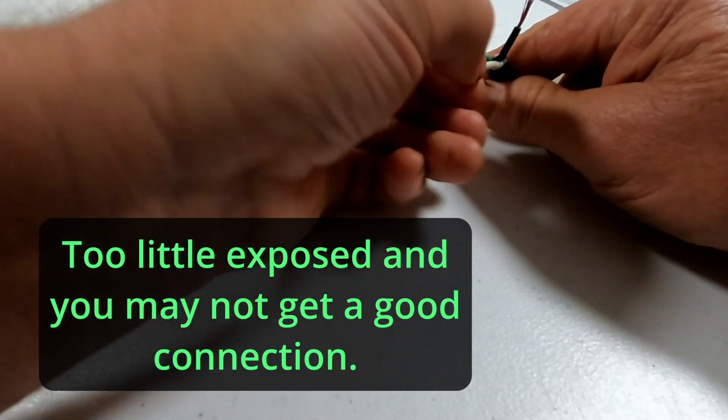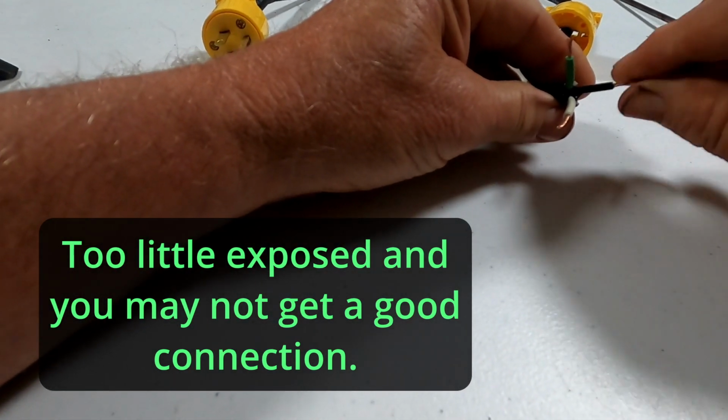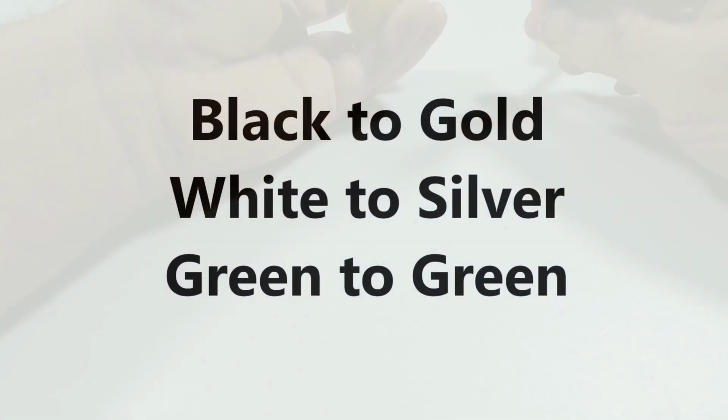This is the female end. This is the male end we've already put on. This is the female end. And the same scenario applies here. The black wire will go to the gold screw, and the white wire goes to the silver screw. And last but not least, the green wire goes to the green screw.